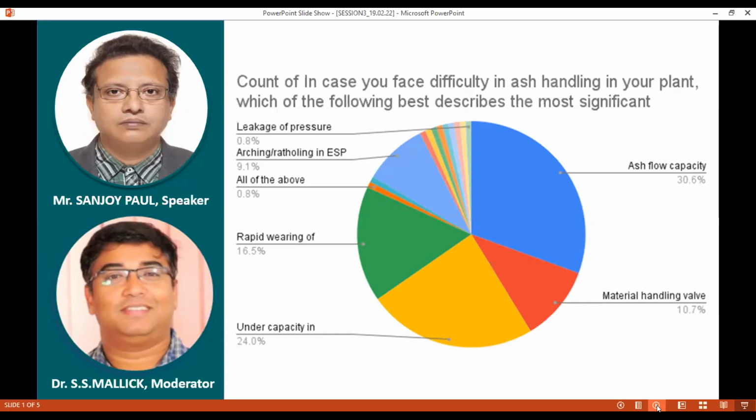At the engineering stage, if the airline is laid at a certain slope, suppose a 2-degree slope, then if any droplets of water are precipitated at the bottom, they will flow in the slanted portion, and at strategic points, water tapping valves and draining valves may be provided. This is number one. Number two is that